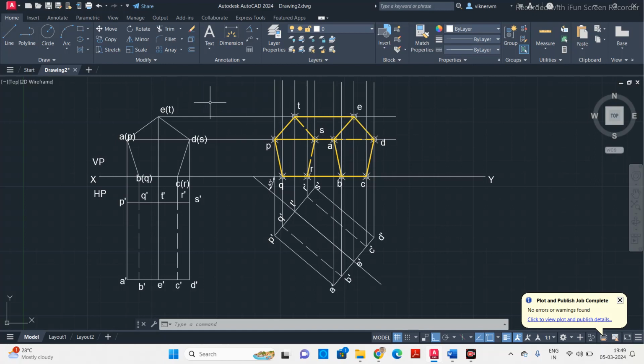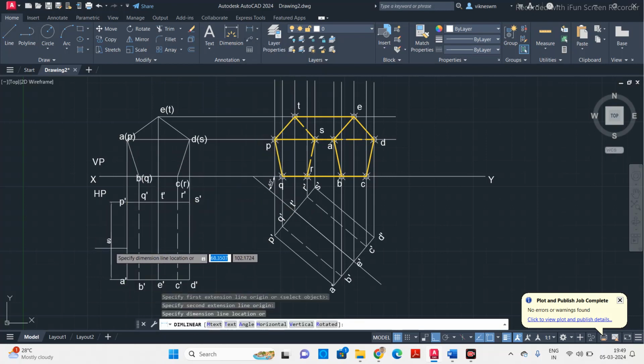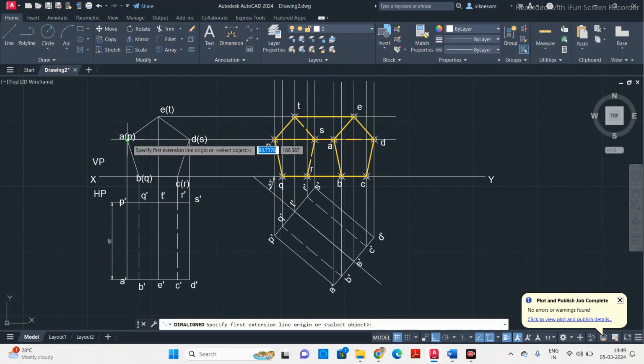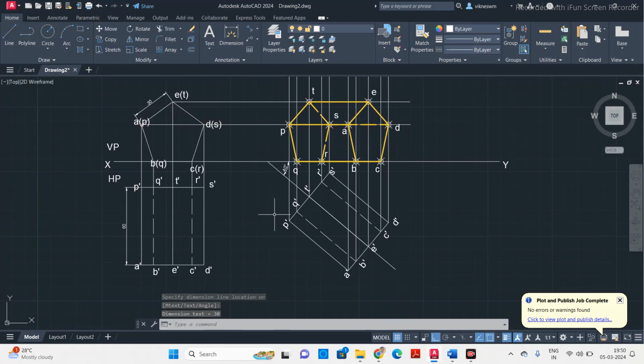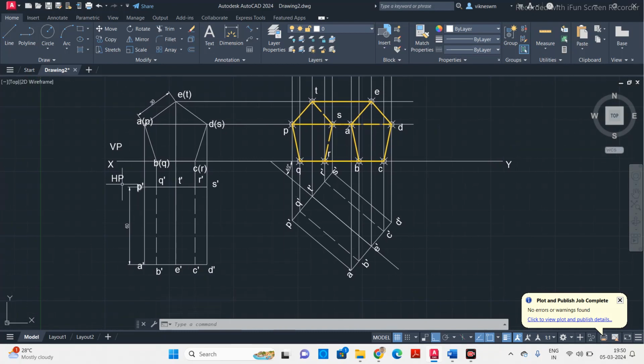Okay. Now take dimensions, take linear dimensions, specify the axis length 60 and take aligned dimension. Click on the two corners. Oh, this is 30. Now the bottom, you have to write. So what is the unit for the dimensions which we used in the diagrams? So it is in mm, so all dimensions are in mm.